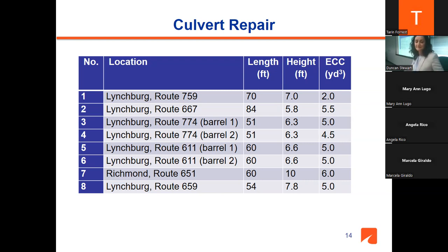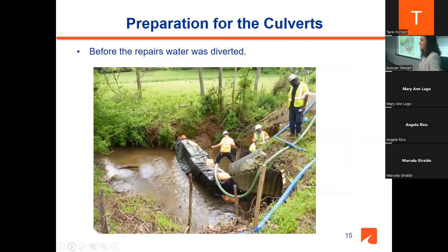And then the other issue is that most of these houses, they hold water. So we try to put some kind of rapid setting cement, and some people say that there's water stopper type of thing, you don't want the water to keep on coming out, mixed with this concrete, because it would weaken the concrete. So we try to, this is still coming a little bit, but not much to a degree that it washes away the water. So we tell them, go ahead and put some rapid setting cement in those holes. And so far, we've been pretty successful with it, and we definitely like to do more.